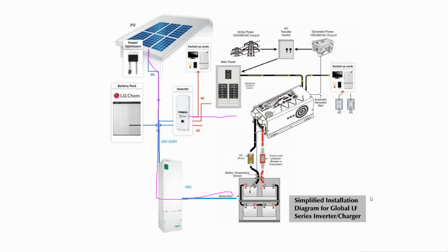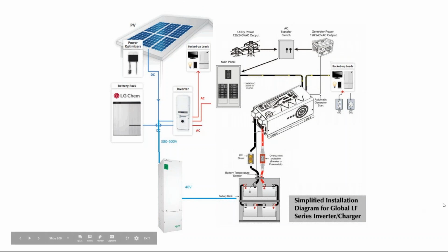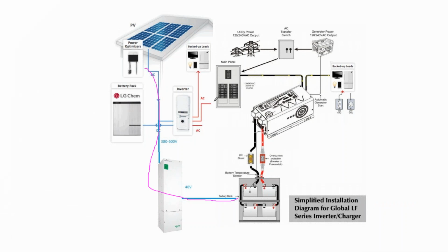The answer is yes. But the battery and the inverter companies will void your warranties if you do. But technically, you can. Now, I've talked with them, and I say, well, what's the concern here? And the concern is that by tapping an additional charge controller onto that bus, not enough power makes it to the inverter, so the charge controller ramps up and sucks the power out of the line, and then the inverter turns off.